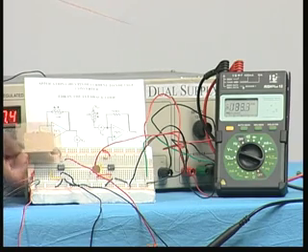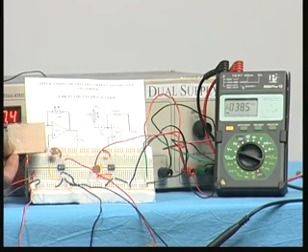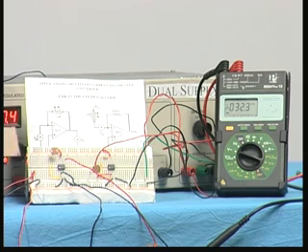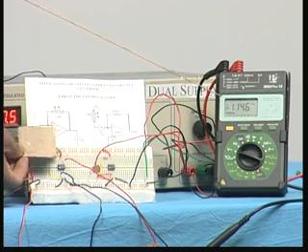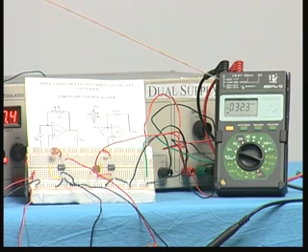That is because when the light is stopped from the LDR, the resistance of the LDR increases, we all know that. So you can see this can be used to detect light intensity. When I close the LDR, the resistance increases, the output voltage increases. When I remove the lid, then the LDR is exposed to a lot of light, and therefore the resistance is small and the voltage is also small.